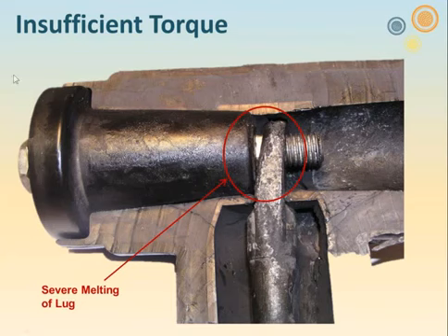And the way we finally determined that there was insufficient torque was we looked at this surface on the back side. It looks a little distorted here, but it was actually straight. And we saw black marks around the entire surface. There should have been a circle 1 1/4 inches in diameter, which represented the bus bar in the bushing. You're going to see this a little bit later. It's much clearer in a different picture and a different phenomena.